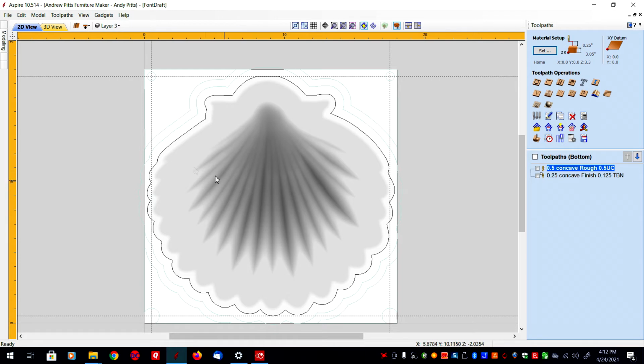The first thing I did though was, and you can just barely see circles up here in the corners, I ended up using 4 long, I had these 3-inch long screws, like deck screws, and since it's a 3-inch long piece, I had to actually countersink 3/4 down. So I took a drill bit and cut 3/4 down into the block, and then drilled the rest of the way for the screws.